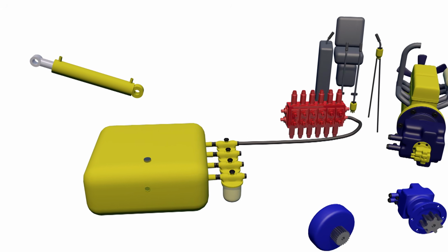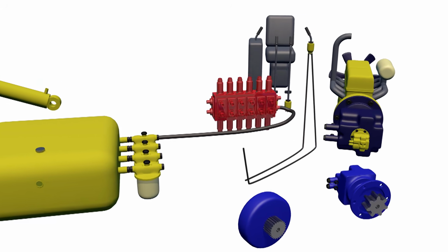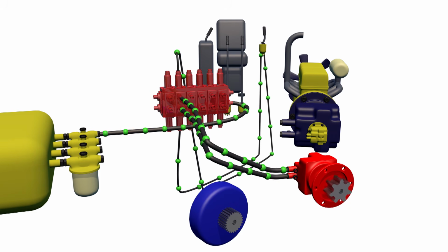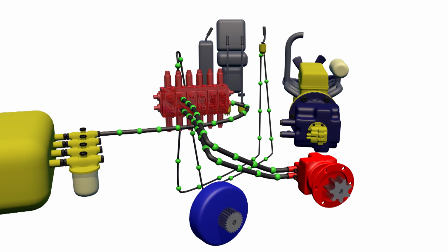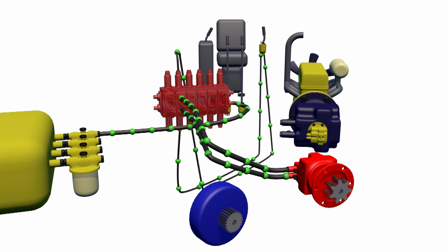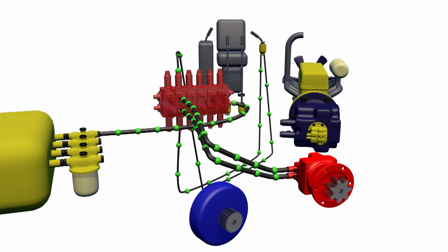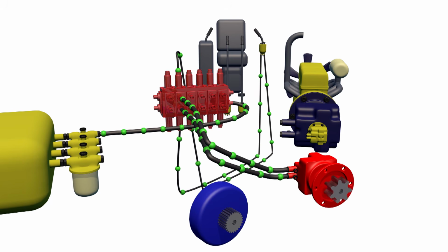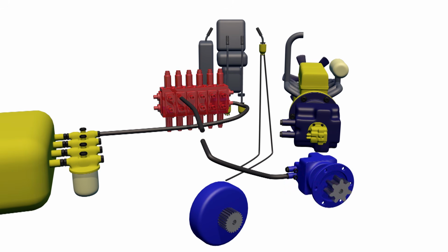The same principle is used to control the rotation of the excavator's swing ring. The swing ring is rotated by a hydraulic motor. It converts the energy of the high-pressure oil flow into mechanical rotational motion. In the most common control lever layout, the controls for the swing ring and the boom are located on a single joystick. The operator controls this joystick with their left hand. When the joystick is moved to the left, the platform rotates to the left. When the joystick is moved to the right, the platform rotates to the right.